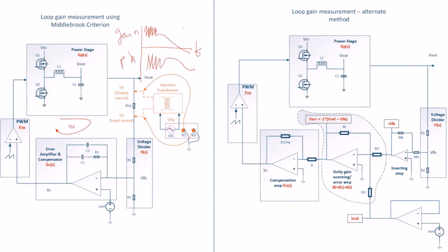I wanted to obtain clean readings in my field, where the power supply must operate reliably with high precision. We use error signals, which is basically the subtraction of the reference signal and the feedback signal in real time, to gain insights about the performance of the power supply.